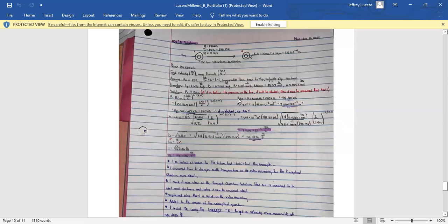I then calculated the absolute pressure, which equals 431.801 kPa. I also calculated the area to be 7.834 times 10 to the negative 9 square meters. This is because to get the mass flow rate, we need the area projected, or the area created by the hole, and we need the initial pressure. So the choked mass flow rate is area times initial pressure times the square root of K times molecular weight over R T initial, times (2 over (K plus 1)) to the (K plus 1) divided by 2 times (K minus 1). When we plug in all the numbers, we get 7.939 times 10 to the negative 9 kilograms per second.